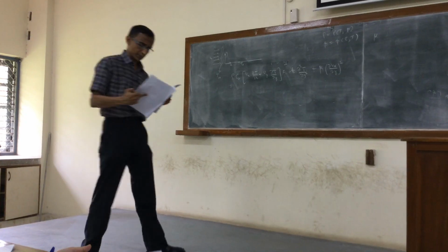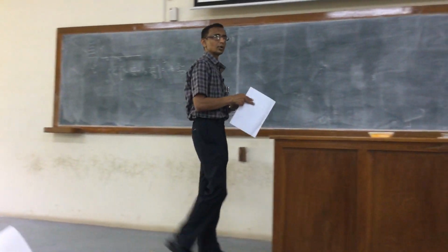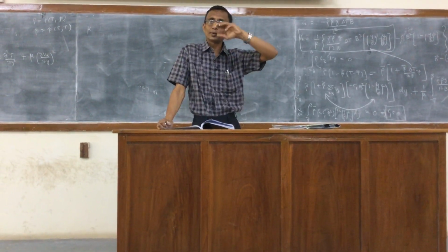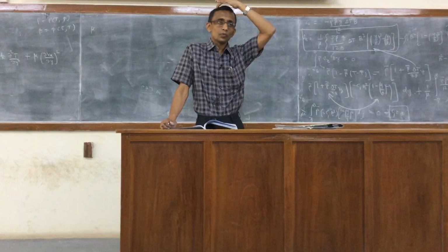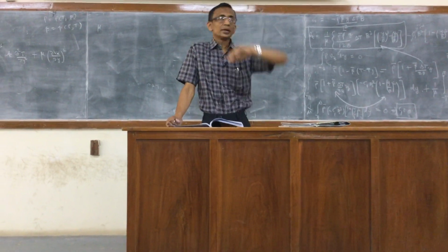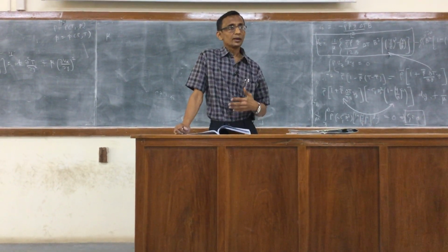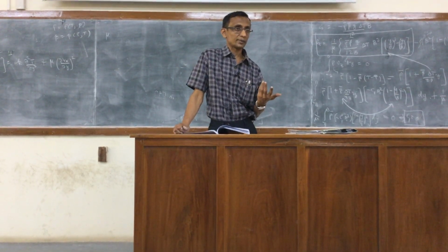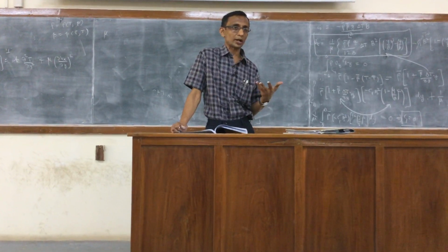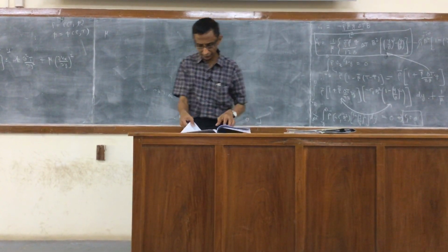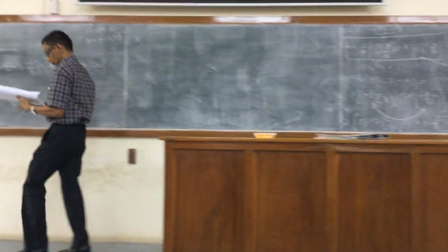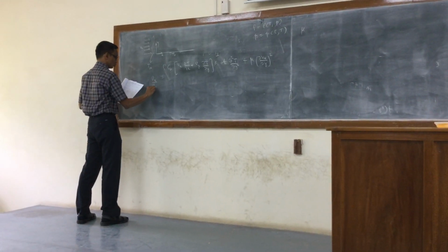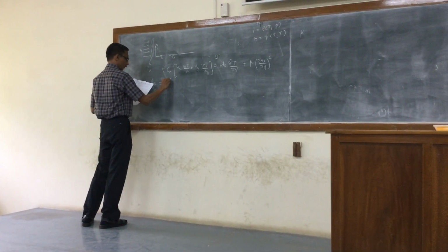What he points out is that in the momentum balance, you have the term coming from gravity, rho g, and there he says you would have to take into account the Boussinesq approximation, and that will in turn affect the results that we have already obtained for the velocity profiles, which were obtained using an isothermal condition. Right? So I am just going to write down the equation, which might be useful for solving problems.